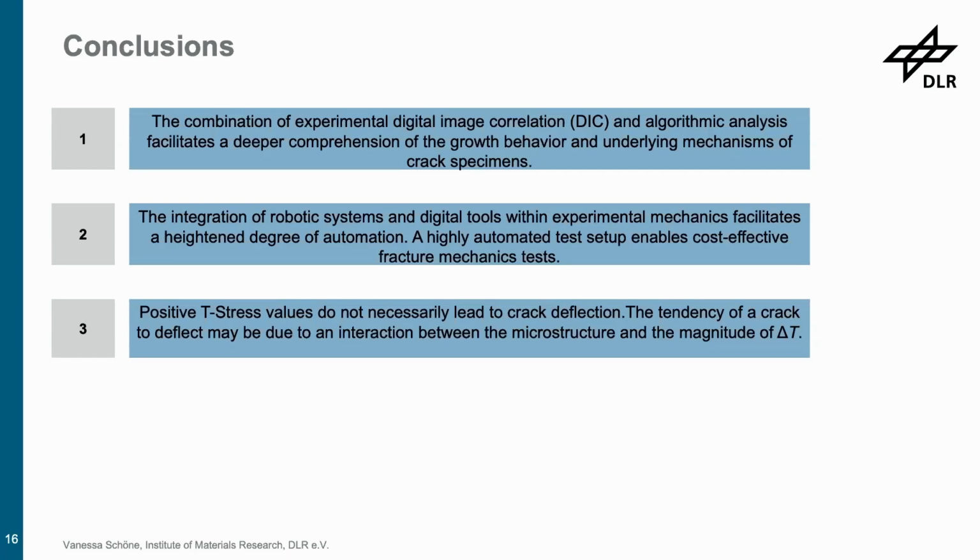Regarding the role of the T stress, we have seen that positive T stress does not necessarily lead to crack deflection, but the tendency of a crack to deflect may be due to an interaction between the microstructure and the magnitude of delta T.